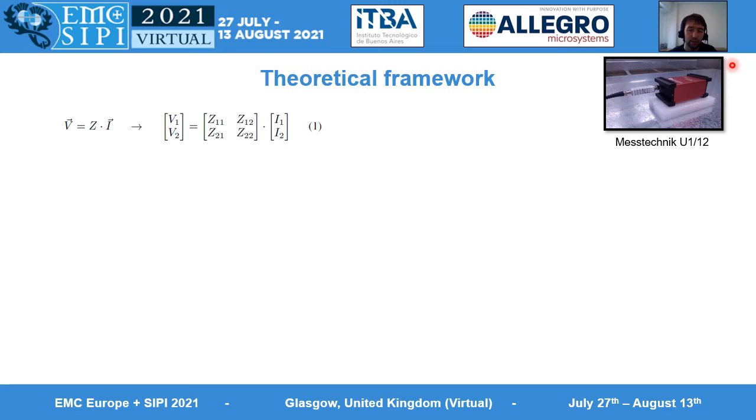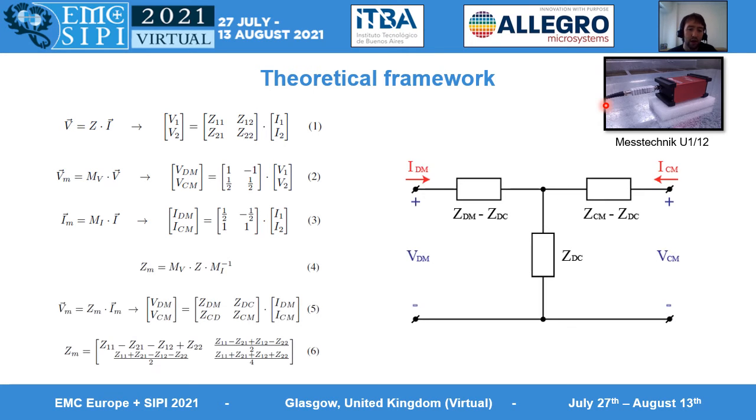So the network that we will characterize is this one. We have our transmitter, the red box here, an anti-aliasing filter, and some input cables. Since this is a 2-port network, we can express the impedance parameters in terms of the single-ended voltages and currents. However, it is more meaningful to express this matrix in terms of the modal impedances. So if we do the math as we've done in the paper, we can come up with this model.